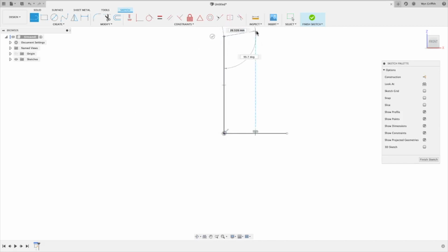And then I'm going to draw a line that represents the top of the vase. And again, you can see that constraint there is telling this line that it has to be perpendicular to the vertical line. Okay, and now I'm going to click the green tick.